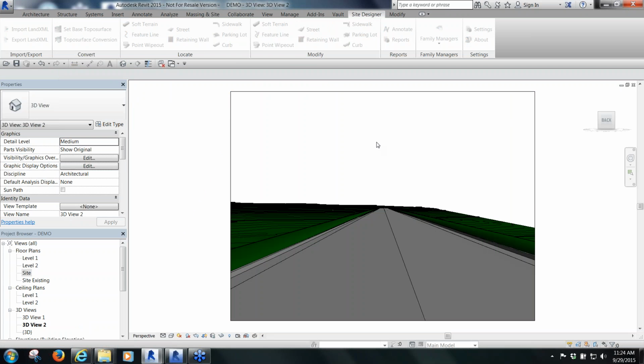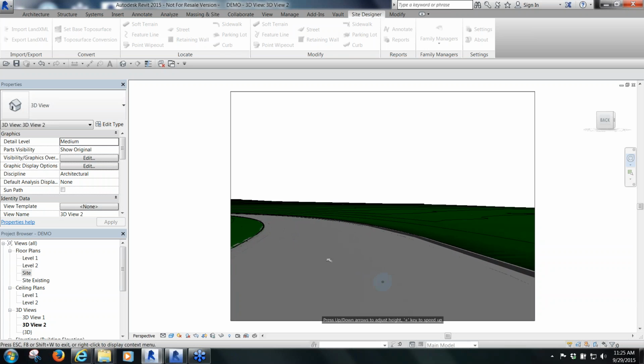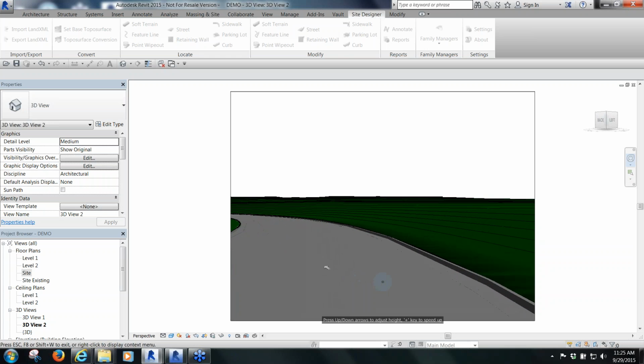Let's do a shaded view. And a lot of people didn't know about this, but you can go over here, click on a full navigation wheel, bring it over here, click the walk button, and drag ever so slowly away from that black dot and blue halo, and that will control the speed and direction. So we're just jogging down our street here. Stop and look at that intersection right there. You can see the topography going around our bend here.